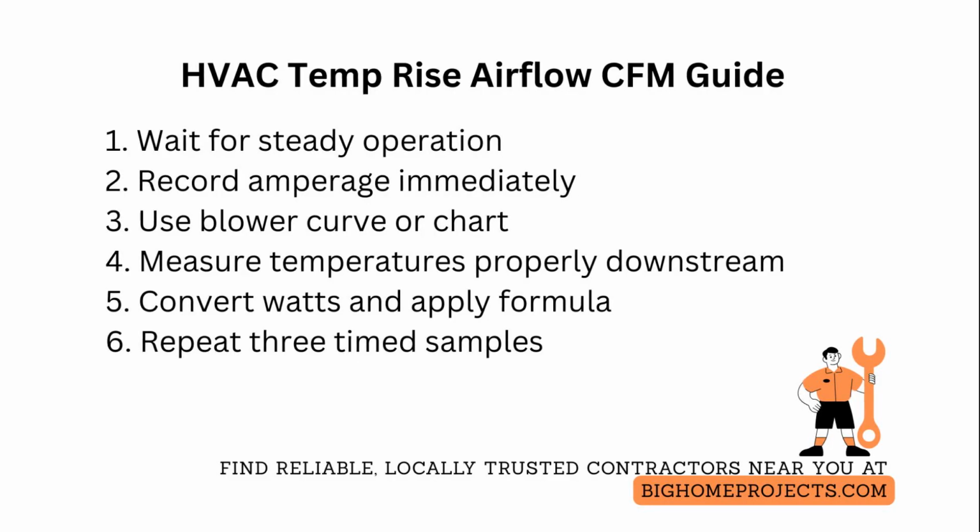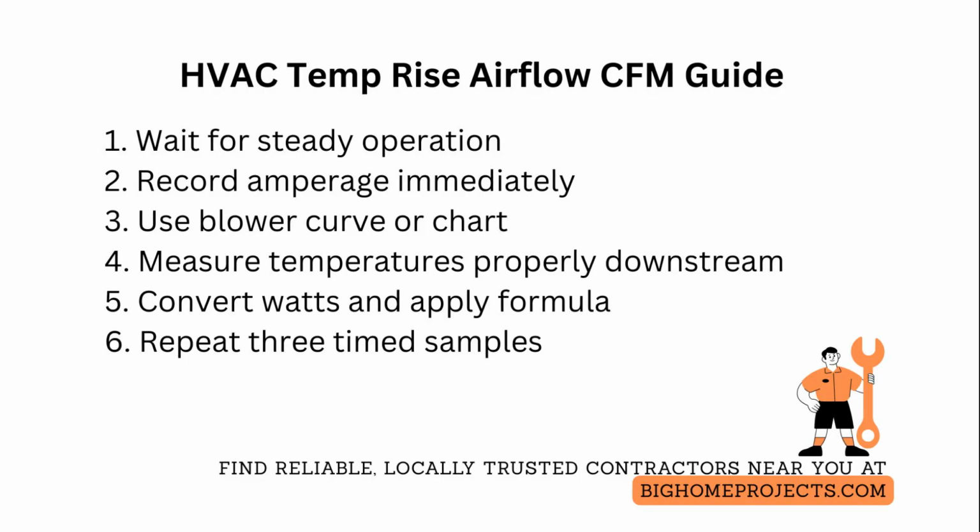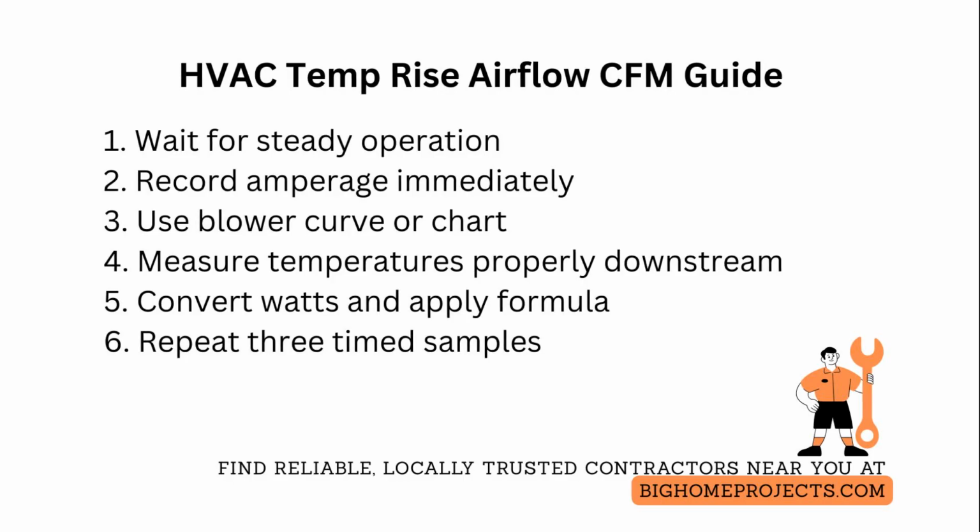Finally, document ambient conditions, duct leakage indications, and filter condition because CFM calculated from Temp-Rise assumes closed system mass flow and clean heat transfer surfaces. If any of those are off, apply a correction factor or run a direct airflow measurement for verification.